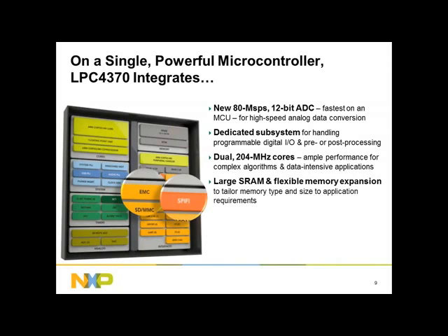On this part, and on many of our 4300 parts, you have some memory buses. We have an external memory controller that allows you to access external SRAM or SDRAM. Depending on the size of the package, it could be anywhere from 8 bits, 16 bits, or 32 bits of an external memory controller. So it allows you to scale your external memory.